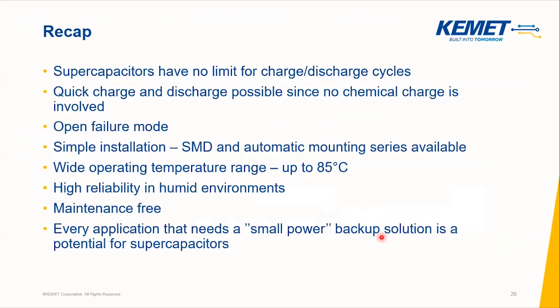So what we went through regarding the supercaps: they have no limit for charge and discharging cycles. They are so quick in charge and discharging because there is no chemical charge involved. It has an open failure mode and is simple in installation. We have SMD and automatic mounting series available, also through-hole ones.